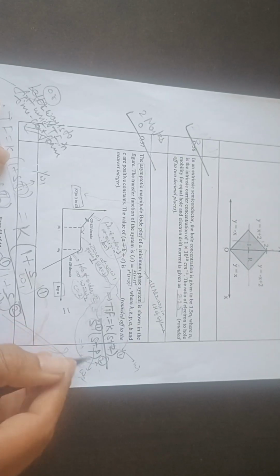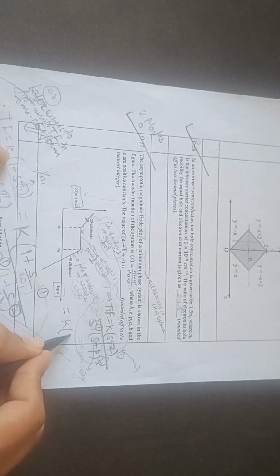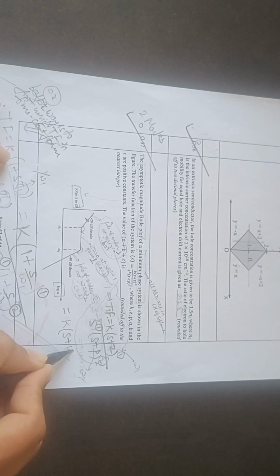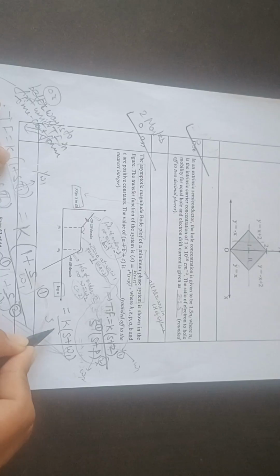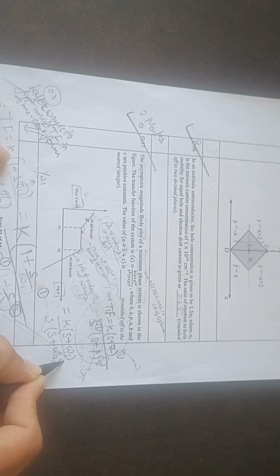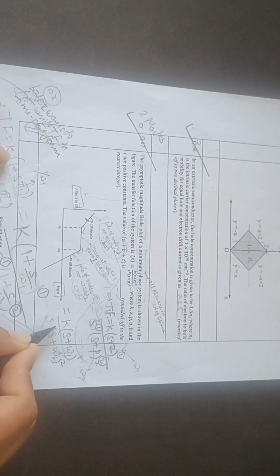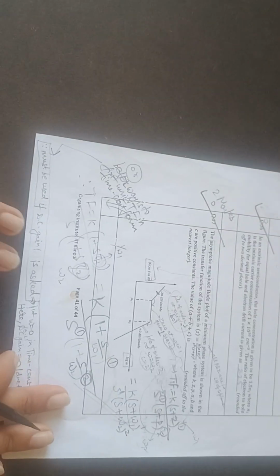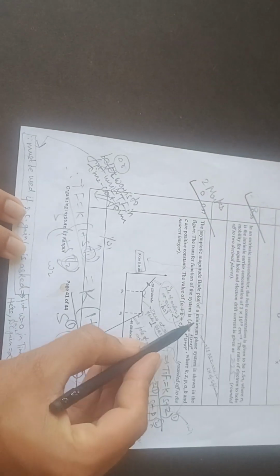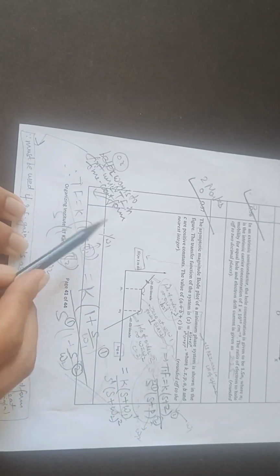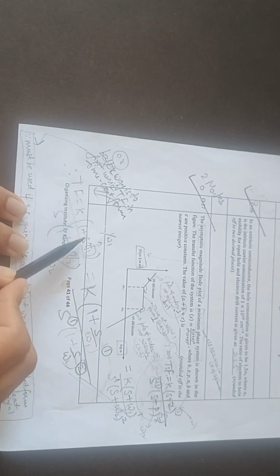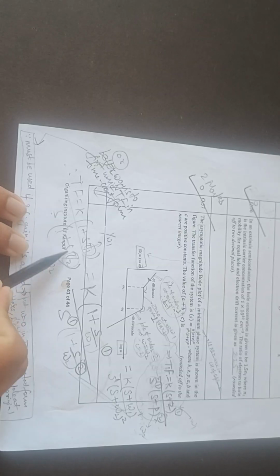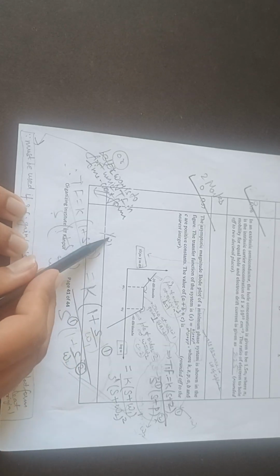So in pole zero form, you can write it as (s plus omega 1) divided by s times (s plus omega 2) squared, with a equal to 1, b equal to 1, and c equal to 2. Or if you want to write it in time constant form, which is always preferred when we also need to find the value of K, then it will be K (1 plus s tau 1) divided by s (1 plus s tau 2) squared, where tau 1 is nothing but 1 upon omega 1.